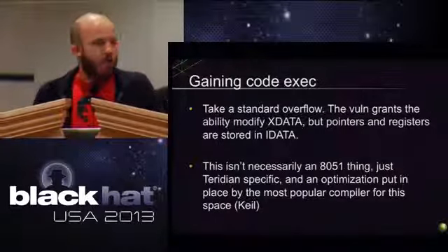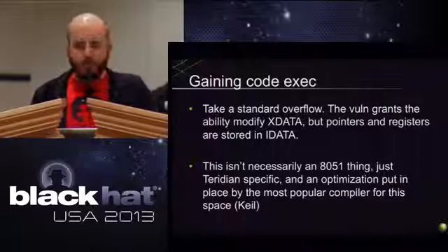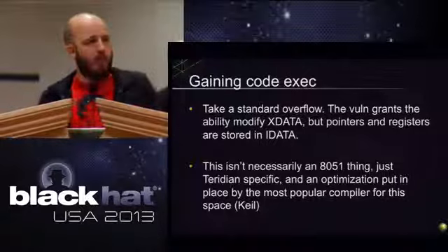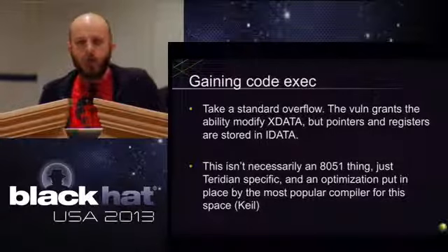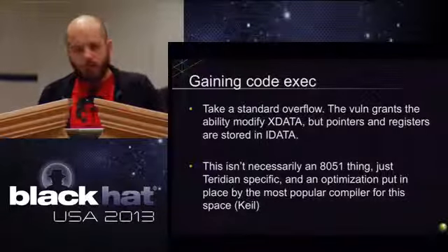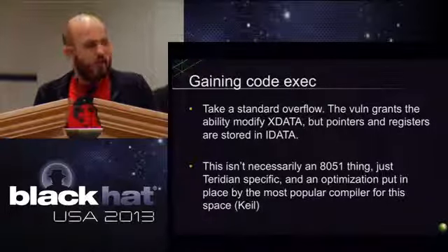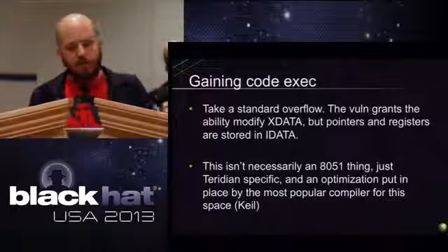So let's talk about a standard overflow, right? So the standard memcopy type thing. Once you've got whatever that type of bug would be, you've got the ability to make modifications to X data, right? But there's nothing important there. So how do we do it? And it's not necessarily just an 8051 thing that this does it, but it's Teridian specific.